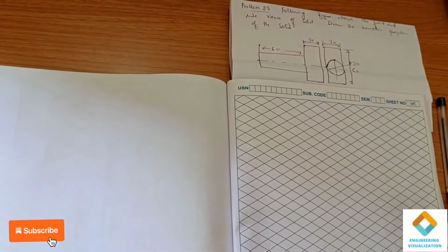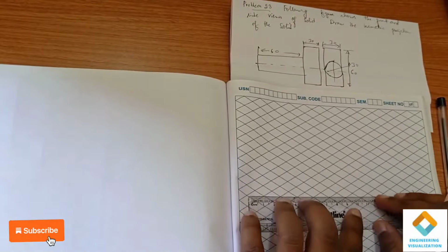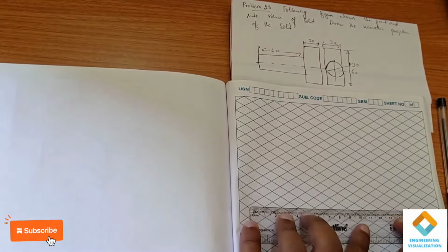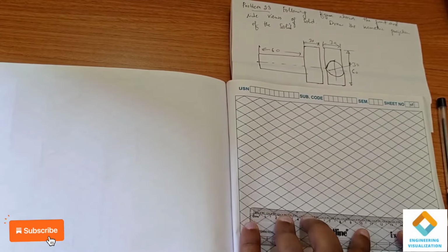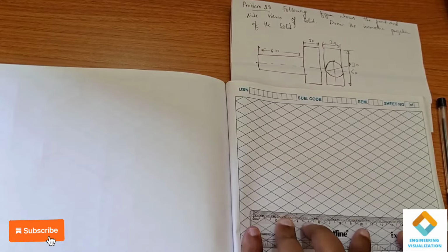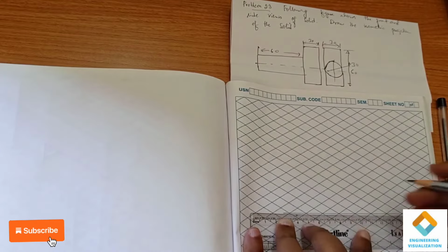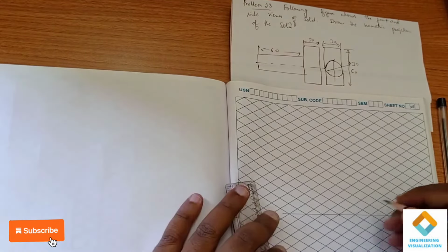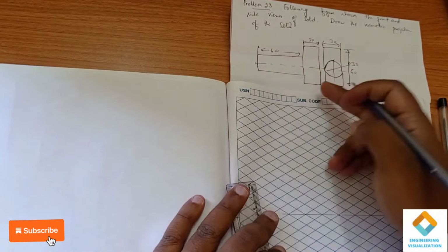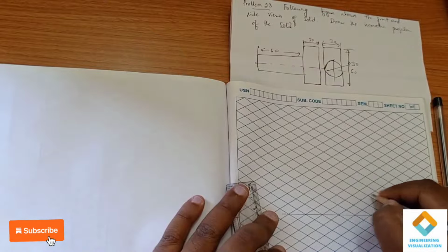We are going to do this problem similarly, using the side view. Just see how I'm going to do this problem. First I will be drawing the reference line here. Now from this end I'll be leaving a distance, because you can see that this is a cylinder extruded from the center of it, so we have to leave the 60 mm distance, that is 6 boxes, 1 2 3 4 5 6.